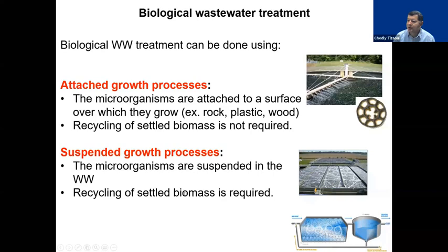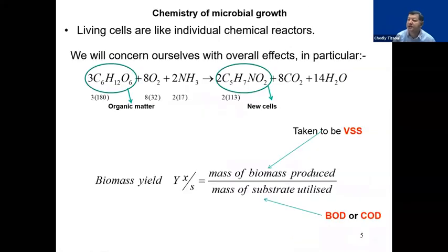The other way, by the way, to suspend the microorganisms, you could have your reactor like that, and if you have a high-speed impeller, well, I wouldn't say high speed, but it's at the right speed. It's not slow as well, so it has an optimized speed. That speed keeps agitating the top layer of the liquid, what's going to happen? You're going to suspend the whole volume of the liquid as well. So that's another technology which is widely used in the wastewater industry.